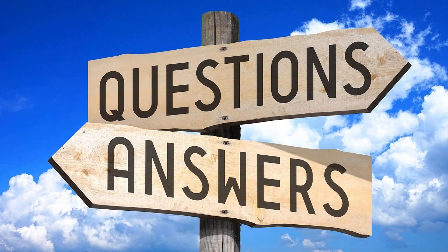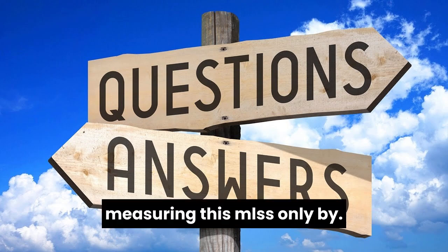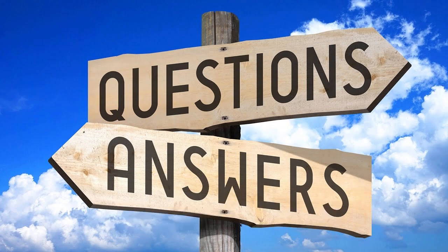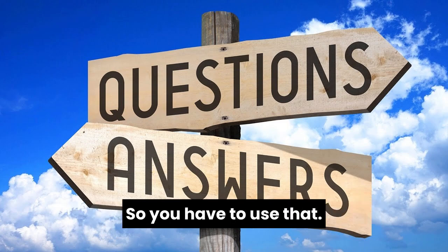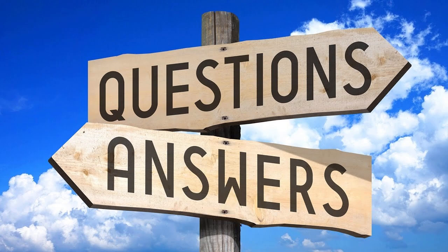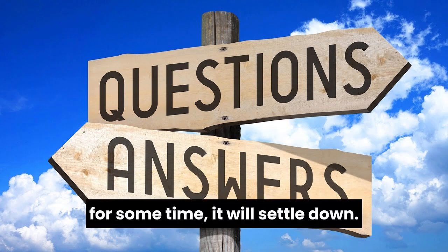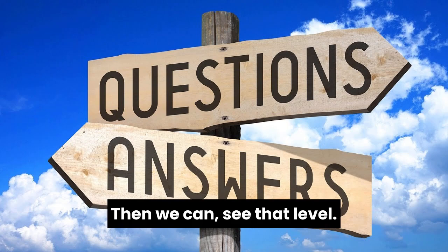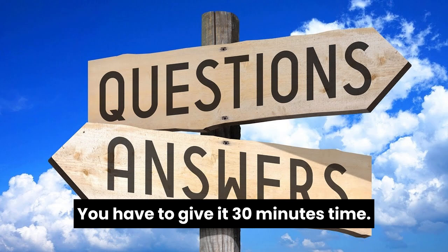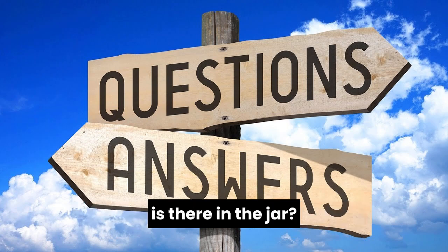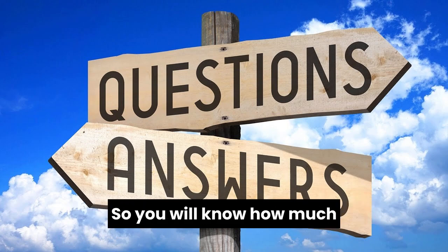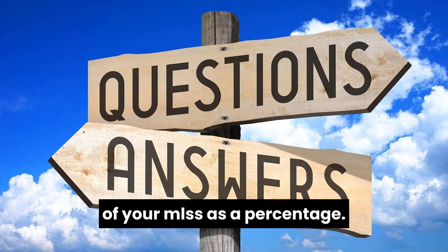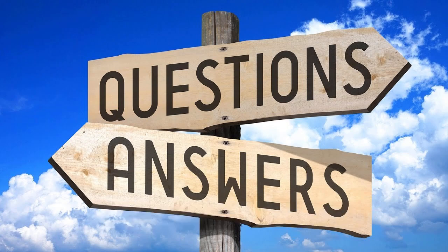Sir, is MLSS measured only in a transparent flask? Yes, MLSS measurement jars will be there, so you have to use that jar. Fill it and leave it for some time, and it will settle down. Then we can see that level. You have to give it 30 minutes. After 30 minutes, see how much is there in the jar. The jar will have measurement gradations, so you will know exactly the volume of your MLSS as a percentage. Okay. Thank you, sir.